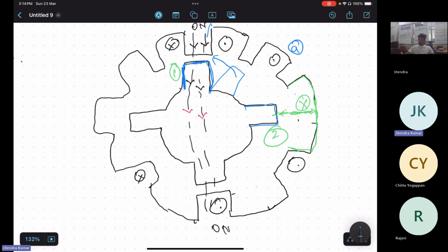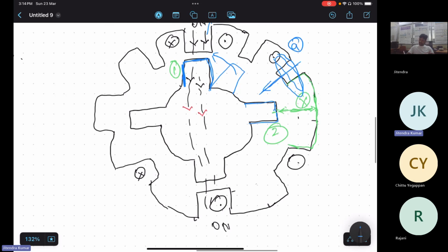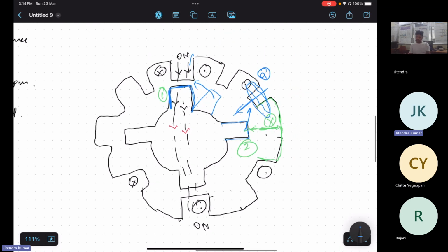Because of this winding, the stator force will be produced in such a manner that rotor tooth number two will be attracted to stator tooth A. And this process is continuously repeated, switching off all the stator teeth corresponding to the unaligned position of the rotor teeth, and hence the entire rotation is maintained. Okay, so that was very basic. I explained it in a really crude manner. I hope you got the idea behind the operation.